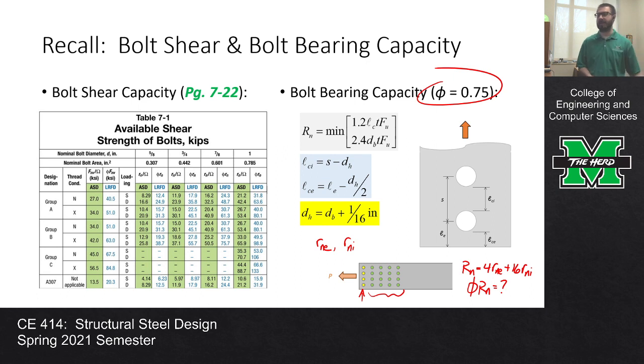In tension member land, we added an extra 1/16 because we weren't sure about that lip of material transmitting load to the rest of the member. But we're not looking at the rest of the member. We're looking at the connection region itself. So we only add.